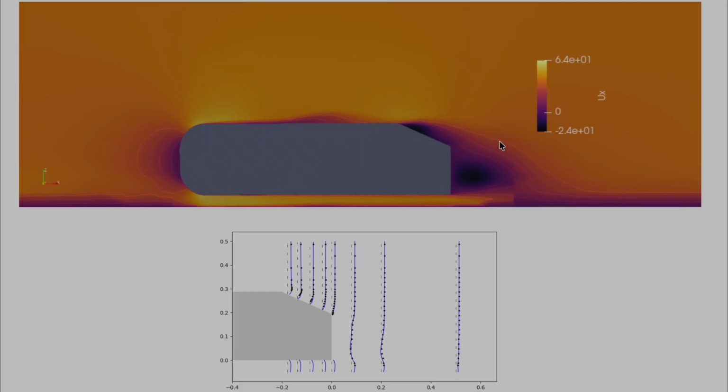Here we can see on the top my velocity profile. Specifically, we're looking at the UX component. And this is over the mid-plane, so the y=0 plane of the simulation. And we can see my data on the top, and we can see some of the experimental and validation simulation data below. And while I'm not able to plot the velocity contours the same way they have, we can see that the trends are very similar, right?